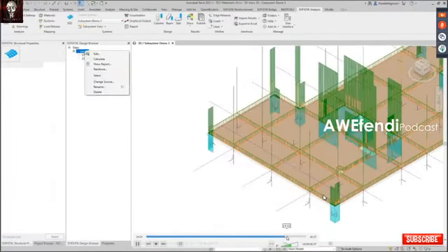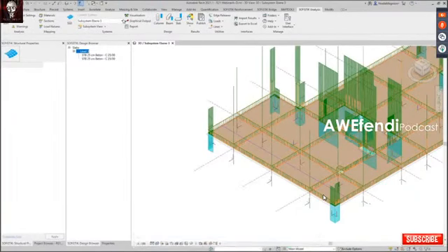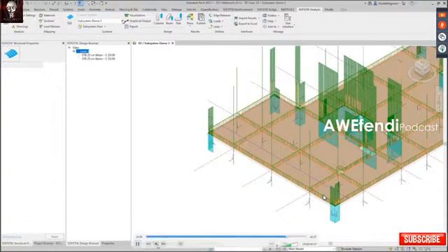And want to mention, of course, I just showed you in the video right now that you can do this with global load combination because this is quite new feature. But as my colleague mentioned, you can also do it with a load pattern display, and you could just switch the filtering and trigger the analysis and the design again, and maybe use here the automatic combination of SOFiSTiK to not have to define manually the global load combination with all the single load cases.